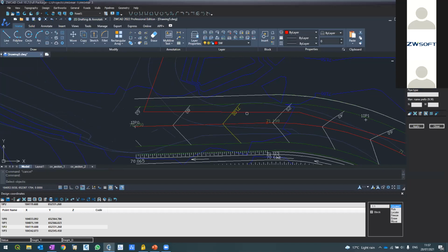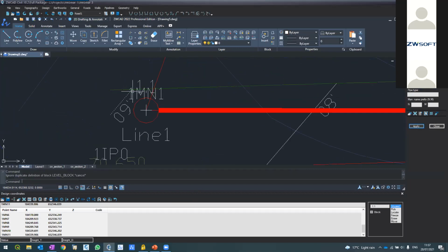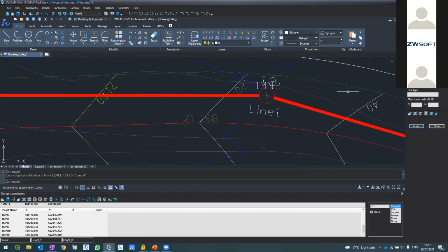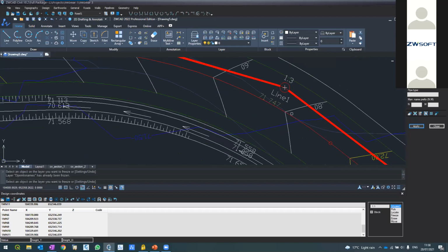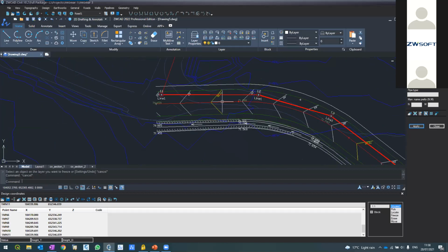So I'm converting this polyline into a pipeline. You see the list of manholes is here. If I want to see them on the drawing, here they are. See? Manhole 1, 2, 3, and so on. Okay. Now I will continue with the second one, M2, which is also a sewage pipeline.